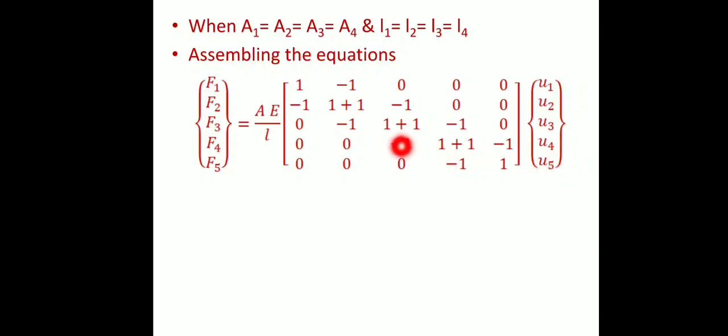The global stiffness matrix is found by adding the element stiffness matrices together: [1, -1; -1, 1] is the stiffness matrix at element 1, and similarly [1, -1; -1, 1] at element 2, element 3 and element 4. E, A and L are taken outside since we assume them constant. In a normal problem they will not be constant, and they should be inside the matrix.